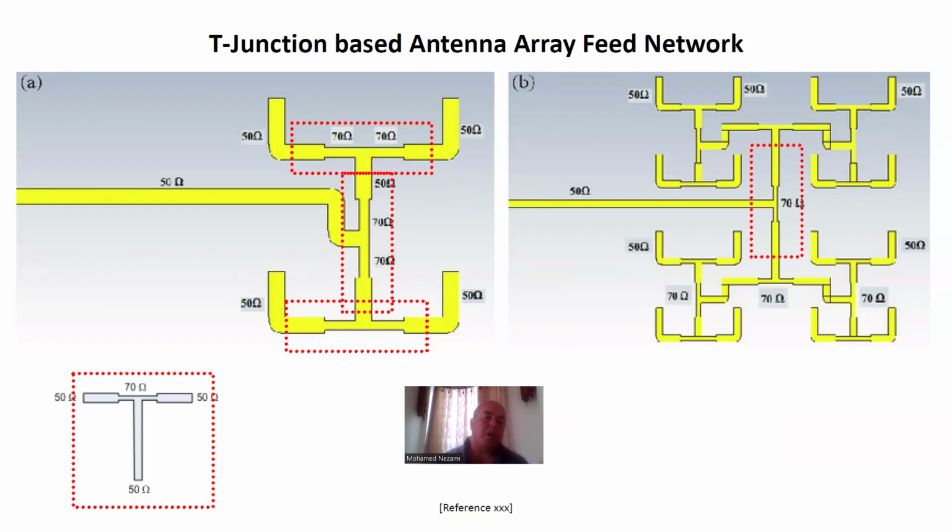So if you come in and decide to use a little notch or some kind of a tweak in the lengths and the dimensions, you basically update that in the entire design, and that's it, you're done. So to make a 16 element array out of this, all we need to do is come in here, basically, grab this here and make two of them. And then just utilize one of these to do the splitting between them, okay? And that's what he did in here.